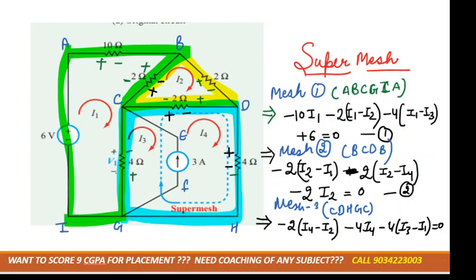Okay, now we have to take an equation from this current source, right? We have to draw one equation from the current source. Can you tell me what would be the equation from the current source? In this, I3 and 3 ampere are moving in the same direction or in the opposite direction? Yes, it is in the opposite direction. So if I3 is in the opposite direction with 3 amperes, so that would be minus I3, right?